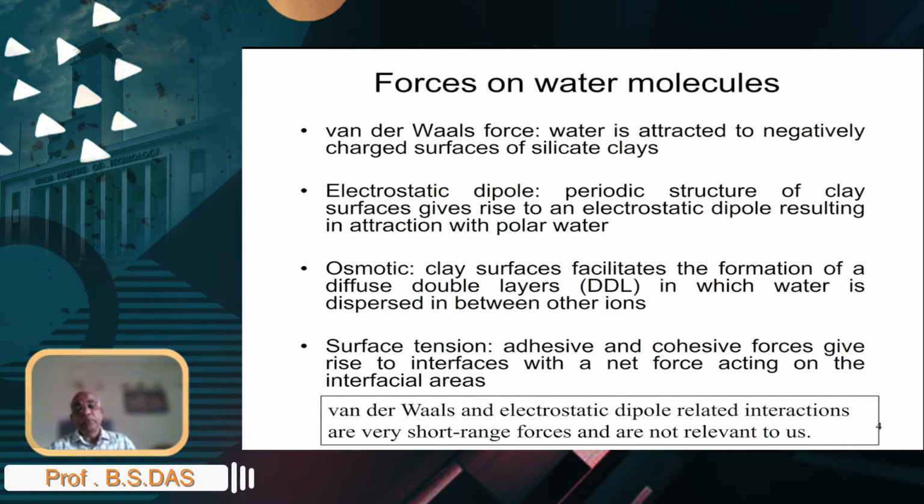The long range forces are basically the interaction between water and solute, that is the osmotic component of the force acting on the water, and of course the interaction between the soil solids and water.